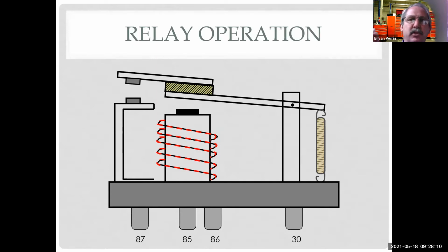And there's some things that the Europeans do really well, and the DIN is one of them. But no, my memory is 86 is power, 85 is ground. Because circuit 30 is power and circuit 31, if I remember correctly, is ground. And you would think that the lower would always be the power and the upper would be the ground, and 85 and 86 are opposite of that. And that's how I remember it. Got to find a trick.